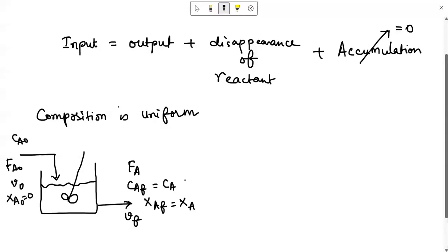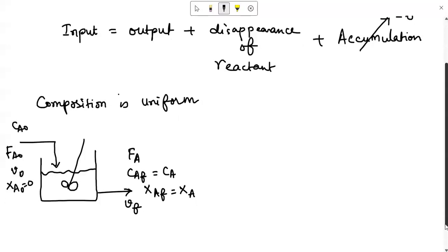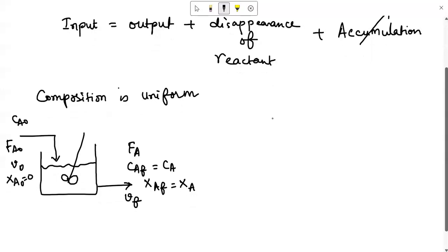Now we are going to write the model equation itself. So if you consider the balance with respect to the component A, then on the input side you have Fa0, on the output you have Fa0 (1 minus Xa). This is how much has converted.